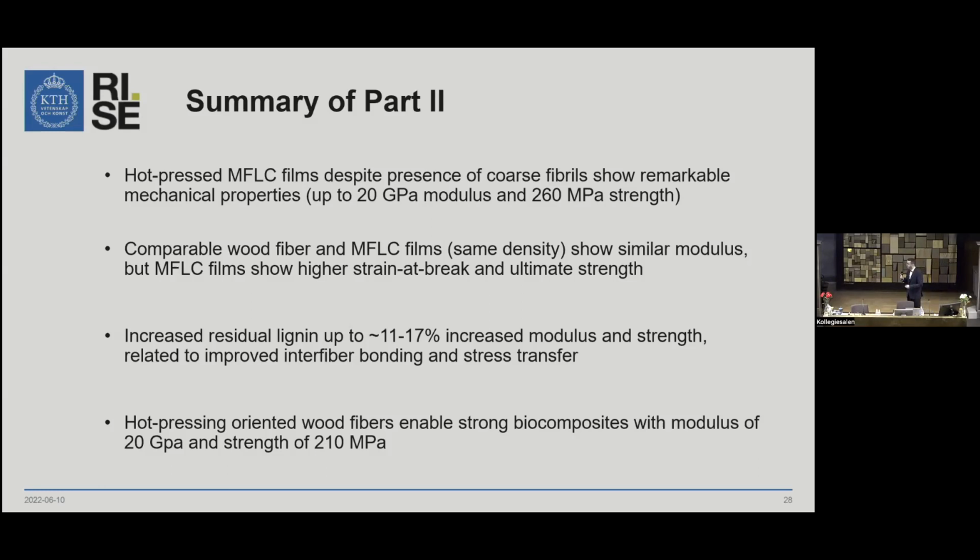And the hot pressing of the oriented wood fibers enabled us to create really strong biocomposites with the modulus of about 20 gigapascal and strength of 210 megapascal.